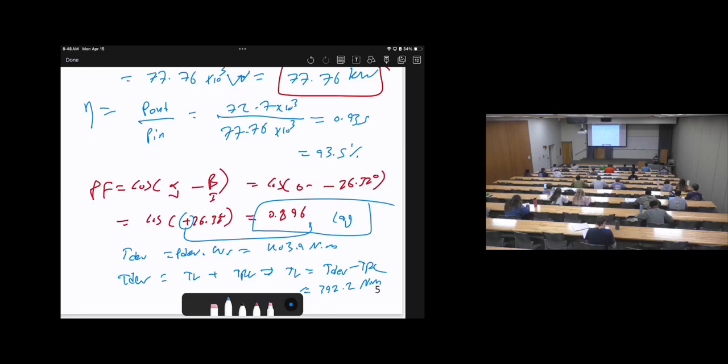Keep in mind, it's very important for you to check the efficiency. You can notice here the efficiency is 93%, or 0.935. If you realize the efficiency is negative, definitely there's something wrong in your calculation. If you realize that efficiency is a complex number, then definitely you substituted the angles incorrectly when you calculated the power. So check your calculations. The efficiency must be positive, between 0 and 1.